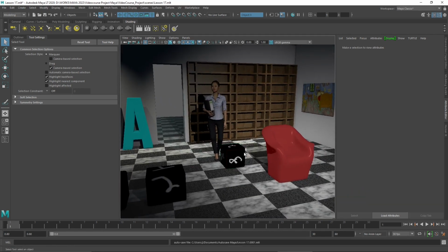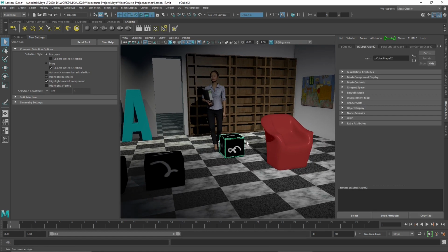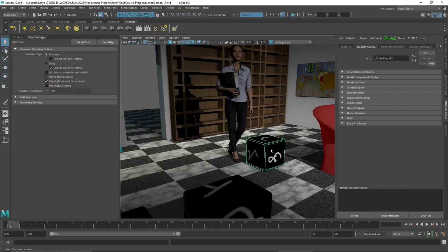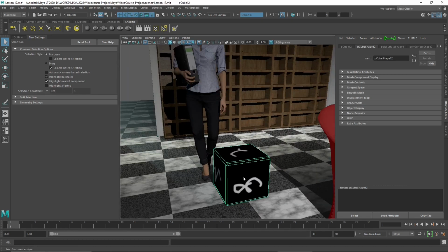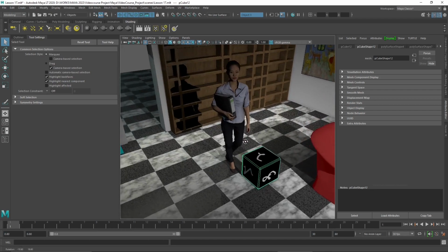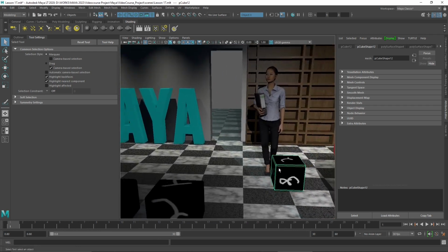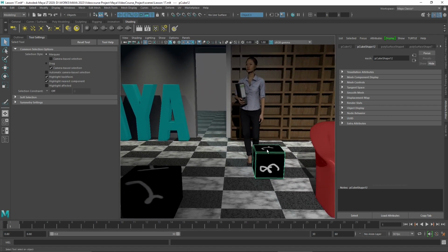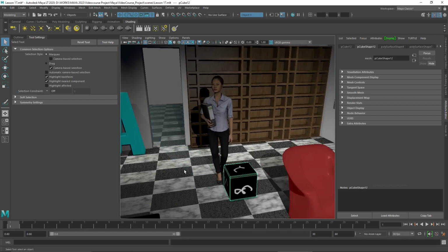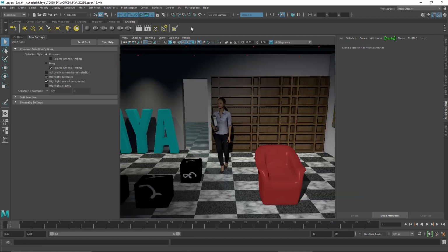And we also talked about unwrap mapping, which is extremely precise when we need to place a material on an object. We made an example with a simple cube. So we created a UV map or a texture. We exported that into GIMP, and then we placed some really simple graphics there just to make an example. But of course, you can use that for packaging. You can use that for industrial design, placing infographics on your objects to do prototyping and so on. So it's a pretty useful part of the Maya software.